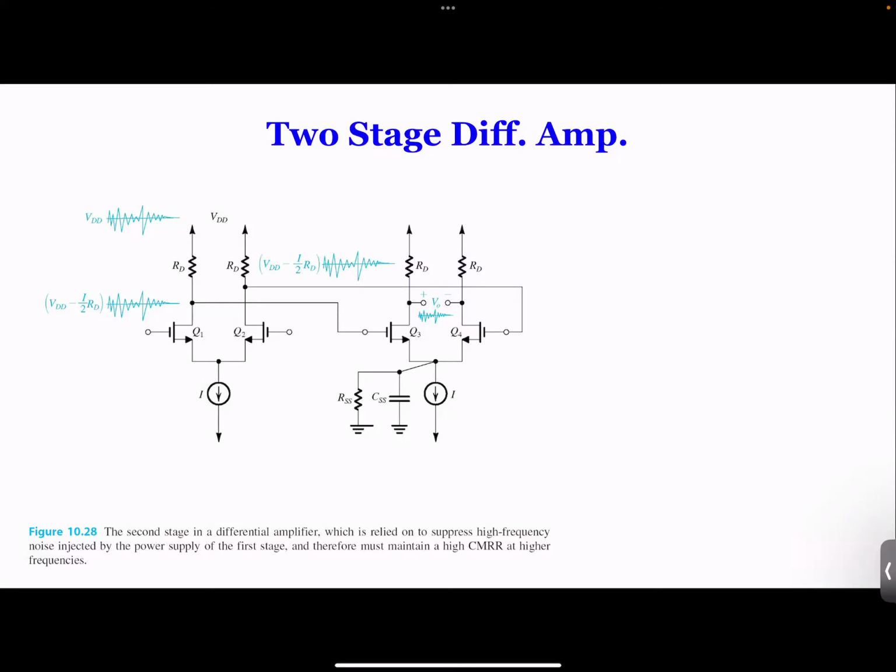You can see the input coming here, and the input coming here. And for each of these stages, you have a current source. So in theory, you will have RSS and CSS at each stage, right? In fact, ideally, you can also draw this over here. And then you can also draw the capacitance over here, capacitance over here, and capacitance over here, things like that, and so on.